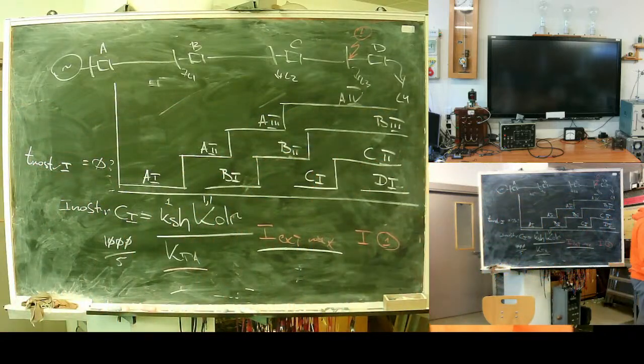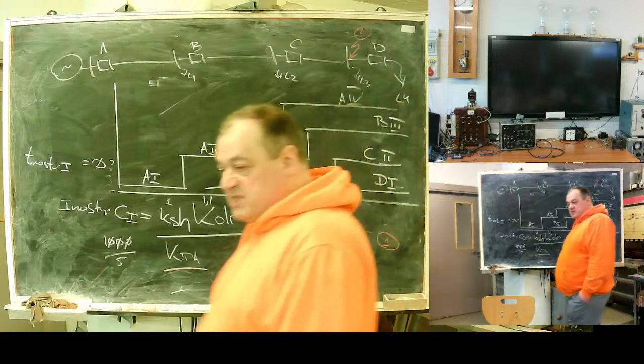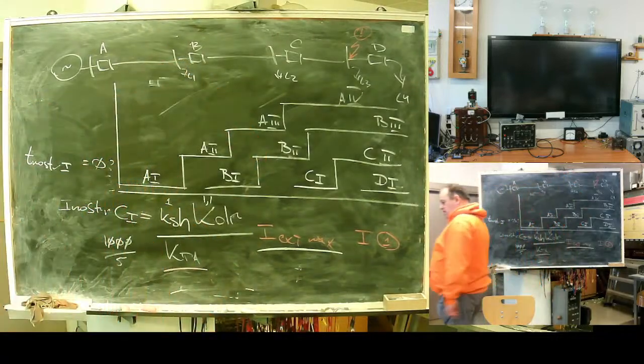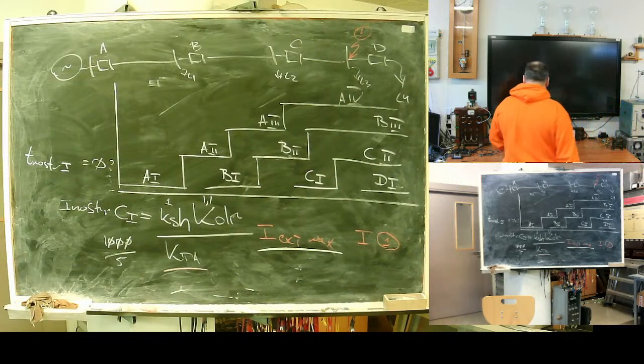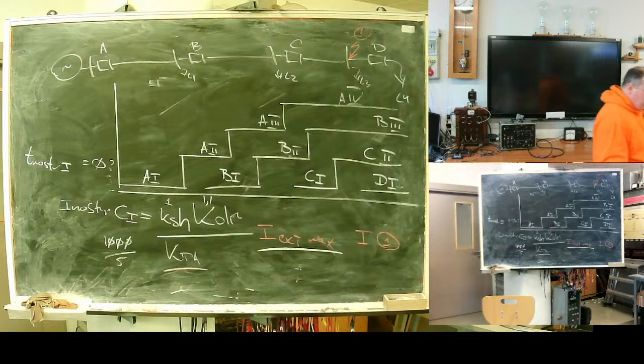All lines have overvoltage protection, lightning protection, starting from the simplest thing like spark discharges and ending with good devices like non-linear resistors, surge arresters. When your line is subject to what? Atmospheric overvoltage or simple lightning.